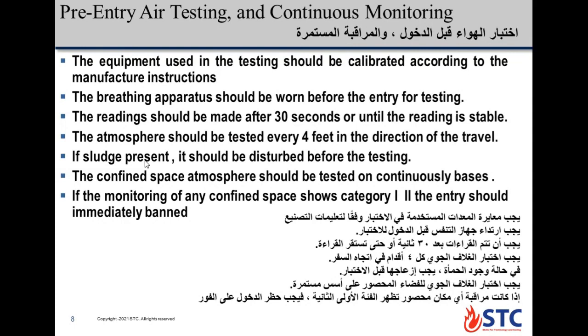The atmosphere should be tested every 4 feet in the direction of the travel inside the confined space. I will show that in video, how to test the atmosphere or how to read the oxygen and the other gas.